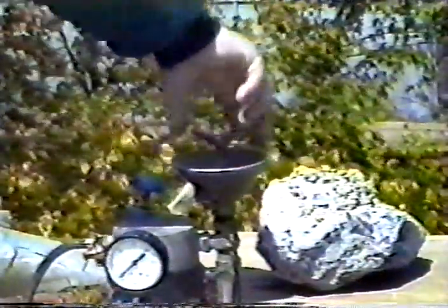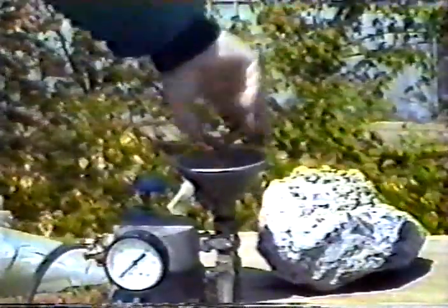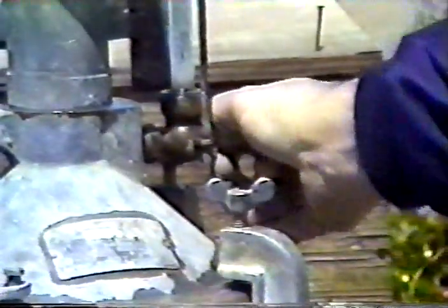Next, water should be poured through the funnel valve until it stands at a level slightly above the arrow mark on the graduated scale. The funnel valve is then closed and the level is adjusted to the arrow mark by drawing off just enough water through the lower petcock.